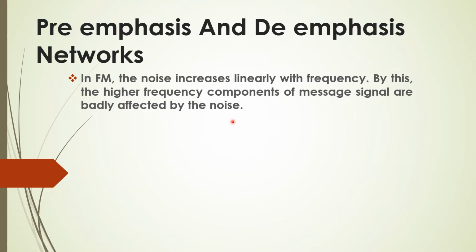And let's see what is pre-emphasis technique. It's a technique where we boost our signal to avoid the noise. At which part we have to boost the signal means wherever we have the high frequencies, at those frequencies only we need to boost up our signals. Because wherever the high frequencies are there, the noise will affect that particular area, so we need to boost those particular amplitudes, then we can avoid that effect of noise.